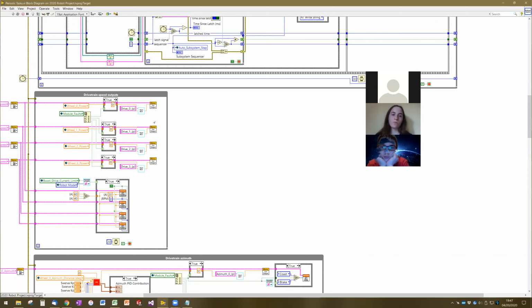There are advantages to doing a more complicated approach. The next advanced thing would be, instead of applying a certain amount of power, apply a certain amount of power that is scaled by the battery voltage. That way, as your battery drops, the motors respond in a more consistent way, similar to how they were with the higher battery voltage.